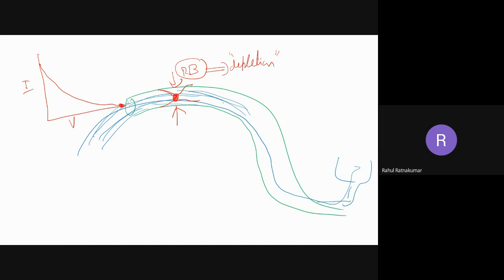This is the best example, water flow. Squeezing the pipe, the channel is reduced and water flow is reduced. Ultimately, if we squeeze further, there will be no flow of water. So there will be a voltage at which current will be zero. That point is called pinch off, and the voltage at which pinch off occurs is called pinch off voltage, V pinch off, or VGS off, because ultimately we are working with the gate source voltage.